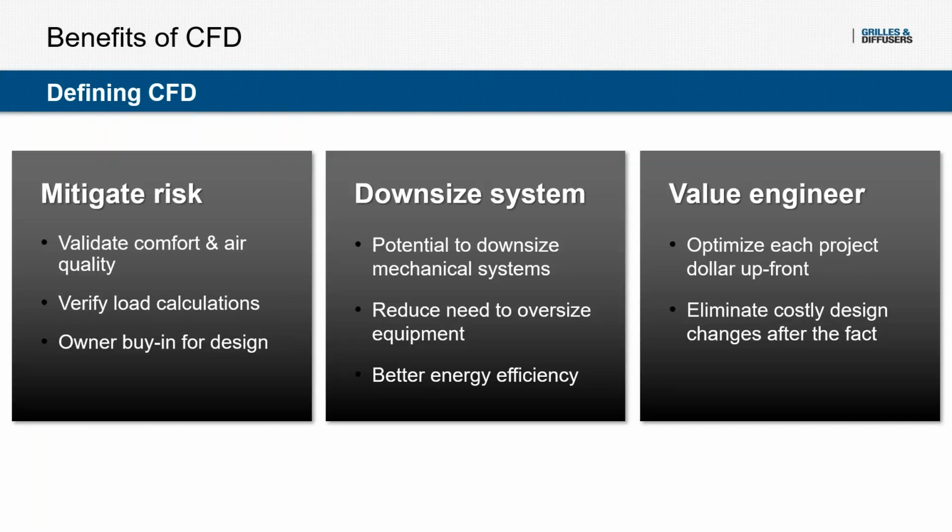And then finally, just to tie off the CFD intro section, the main benefit of CFD for the design engineer is that it's a great way to mitigate design risk. Because you're not only using it to validate how well your design works in terms of comfort and air quality delivered, but it can also be a way to verify load calculations, specifically for the larger, more complicated types of spaces. And that also opens up opportunities to downsize the mechanical system because you're verifying your loads.